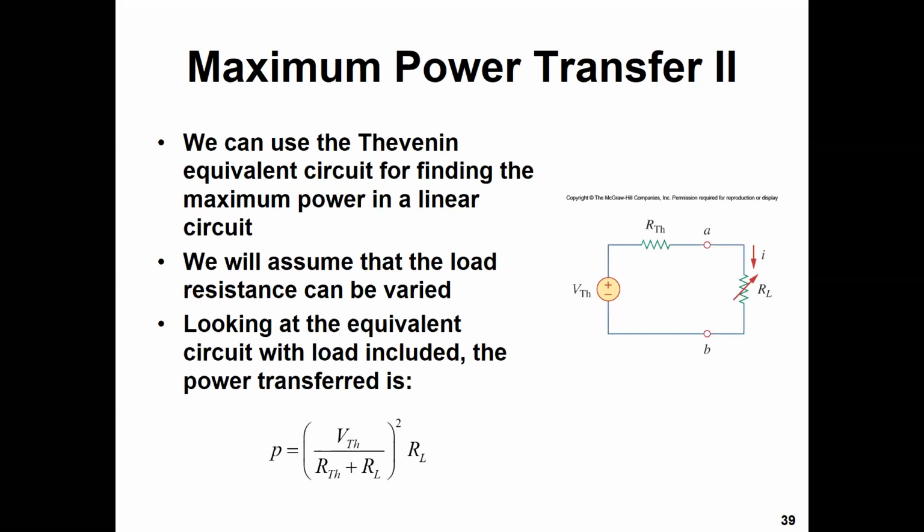So if you want to design a circuit that will draw the maximum power from the power supply to your load, you must design your load resistance to match the R Thevenin value. If you know R Thevenin, then you could design your load to exactly match it, in order to make your design efficient, the best that will draw the maximum power from the power supply.